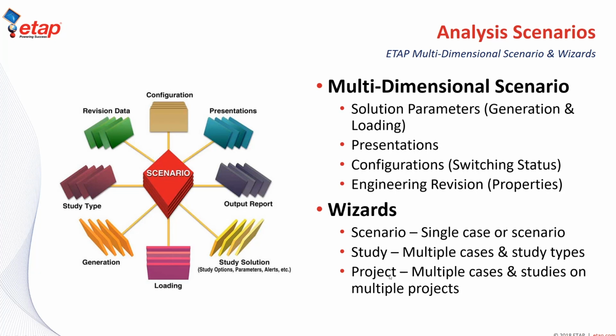You can take this concept one step further with the project wizard, where you can run multiple cases, that is multiple load flow cases, or multiple studies such as load flow and short circuit on multiple projects.